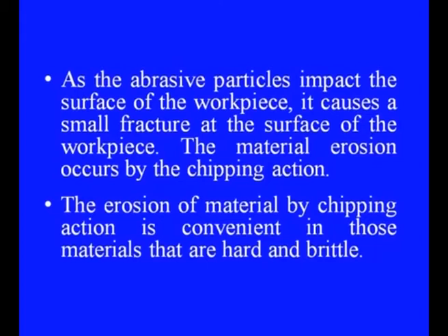As the abrasive particles impact the surface of the workpiece, it causes a small fracture at the surface of the workpiece. The material erosion then occurs by the chipping action. The erosion of material by chipping action is convenient in those materials that are very hard and brittle.